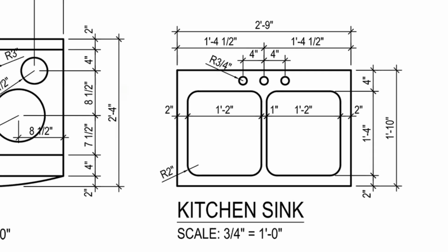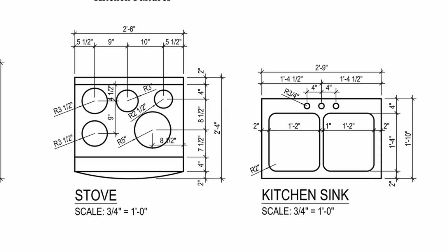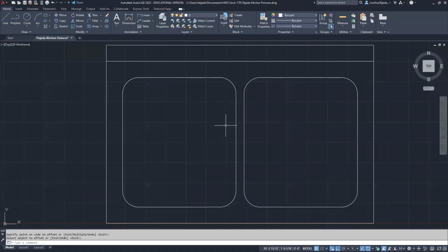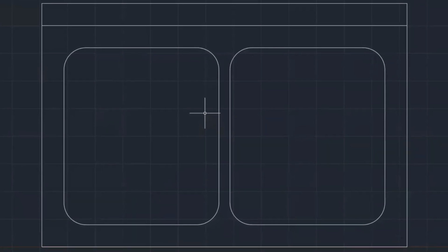The example is showing me that the radius is 3/4 of an inch. So I'm going to draw the first circle in the middle there. So I'm going to head back to my drawing. And I don't need any extra lines because if I select this one, you can see that I have a midpoint. So I'm going to tap the escape key and I will type C for circle and enter. I select the midpoint as the center point of the circle. So I click and I bring that out.